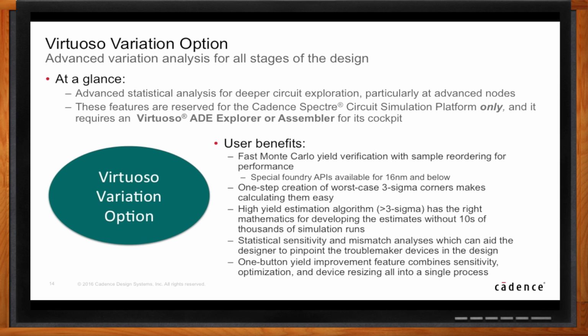And the way that you approach Monte Carlo statistics with those types of designs is different than it was in previous generations. So we've got some great technology that we worked on with a foundry to look at the device physics of FinFETs and to be able to give you great performance on running Monte Carlo statistics now. With a minimum number of runs, you can certainly tell what's going to go on inside of the design, a lot more than what you've been able to do in the past.